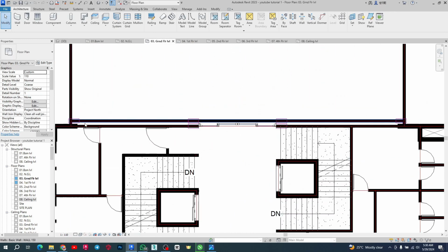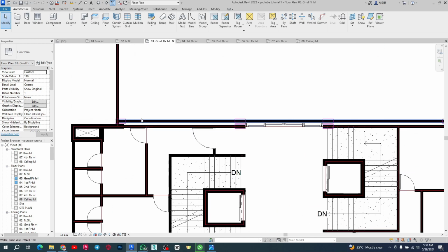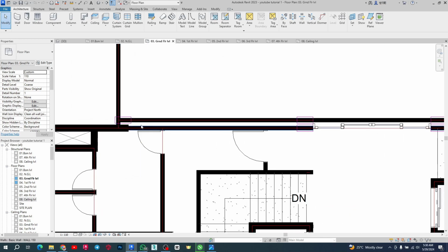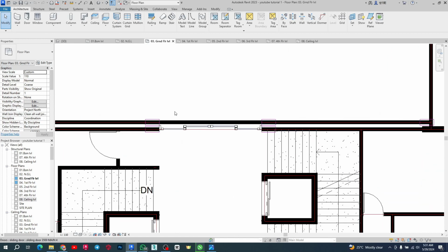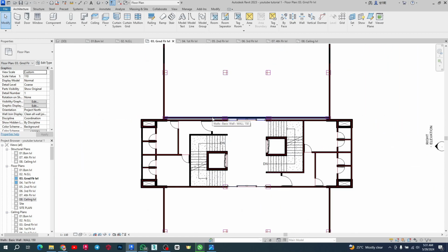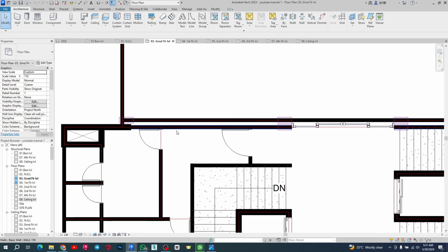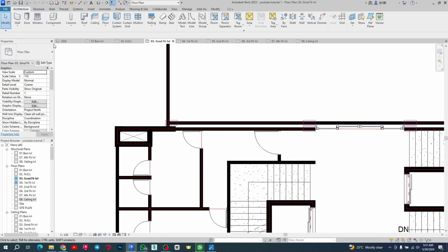Before now, you'll see there's a wall here at the expansion joint. This wall is very important because it's not necessary that we have it here. It's just going to be the beam that is separating. Most often it's the structural element that is used at the expansion joint. So I'm going to create an opening here, just leaving the thickness of the beam available up there. I'll be leaving 700 as the depth of the beam, or 600. Whatever works when we do our analysis is what we use in our conclusion. So let me use 700 for now.